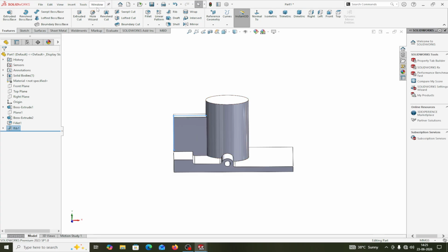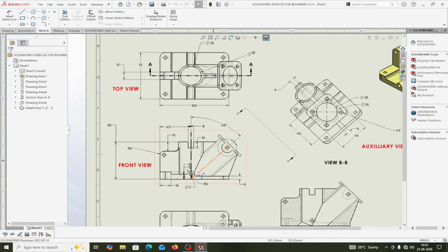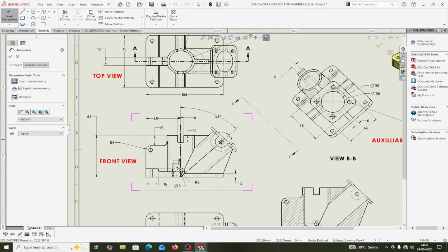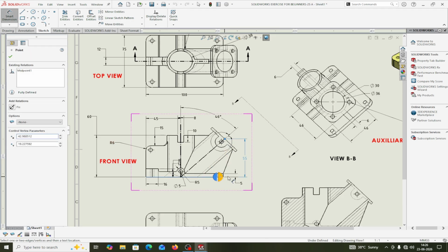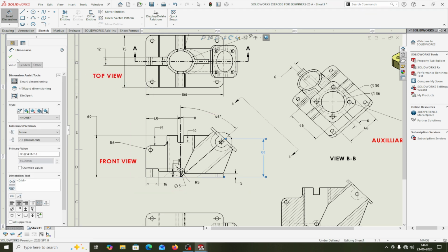Now I make this profile this time. This portion. This pipe is at an angle of 46 degrees from the center line. The height is 55 mm. If you note this height from here to here, this is 55 by default. This one, I will make this circular profile with the plate.